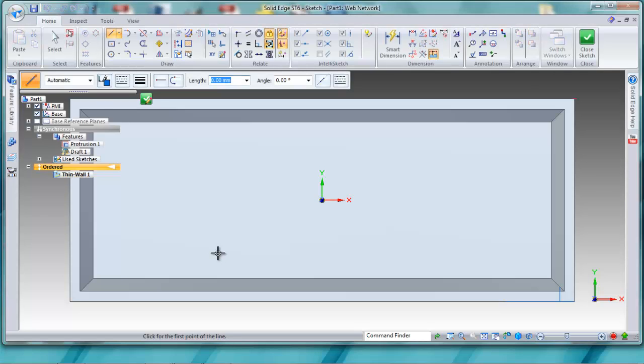And then it automatically just rotates into this sketch mode. So we're going to put a divider line, and you'll notice it'll select either the top plane or this 2mm lower one. So I can find the center point right here, bring it down to this end, and again, watch when it highlights, it's highlighting 2mm below the top of the edge, the top plane. Left click there. So there's my center divider.